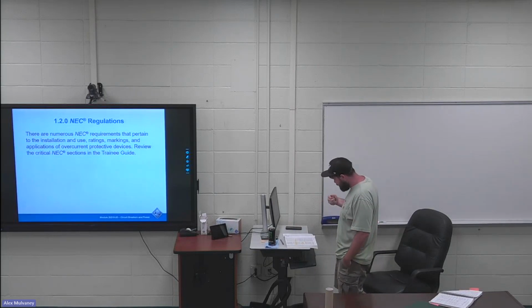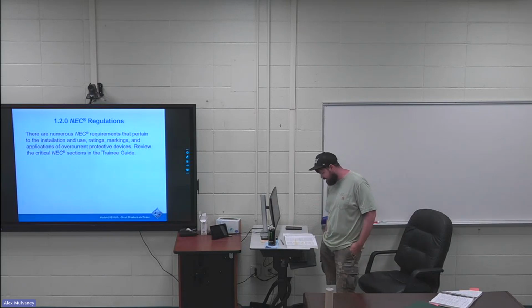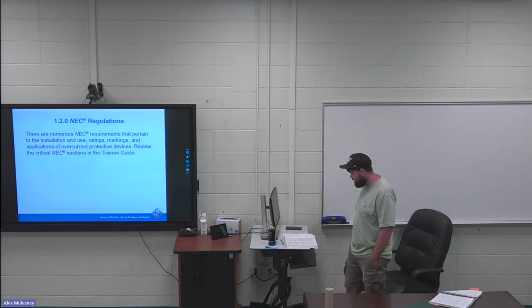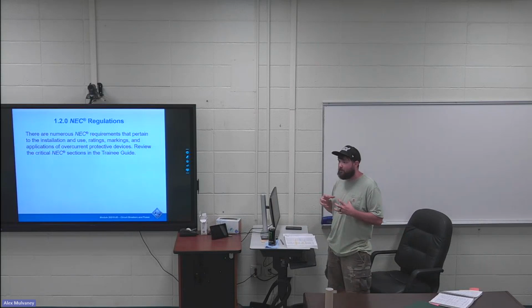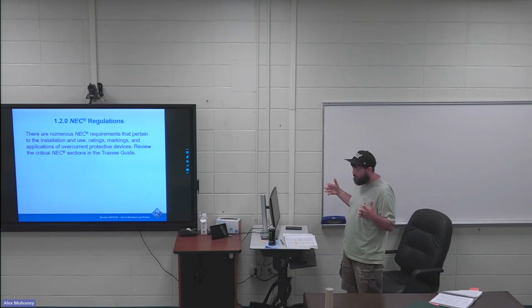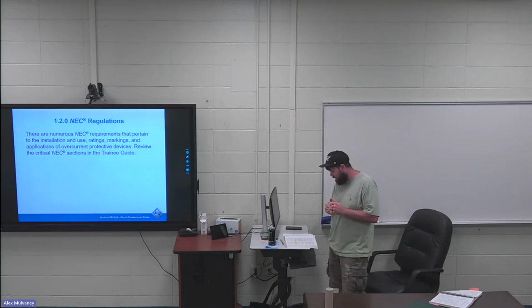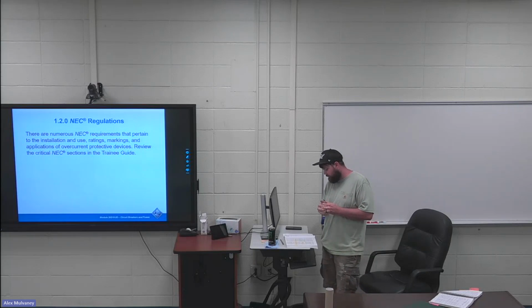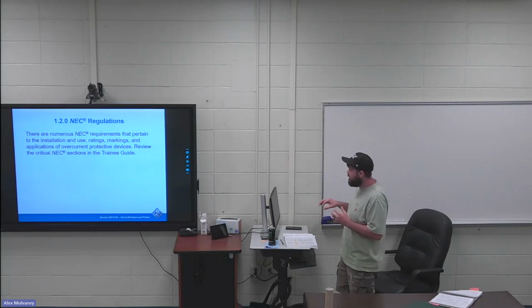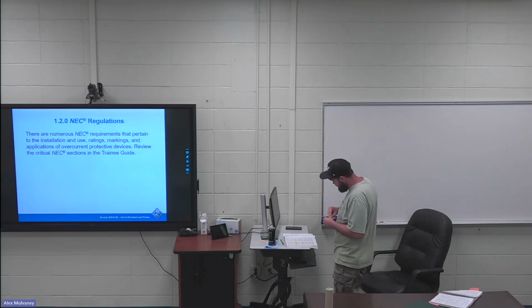Next highlight is the next bullet point down. The whole thing is highlighted. NEC section 240.83(C) is the interrupting rating. This is important. This is the maximum amount of current that any type of overcurrent device can open up. Every circuit breaker having an interrupting rating other than 5,000 amps shall have its interrupting rating shown on the circuit breaker. So if it's not listed on your breaker, then it is assumed to be 5,000 amps.